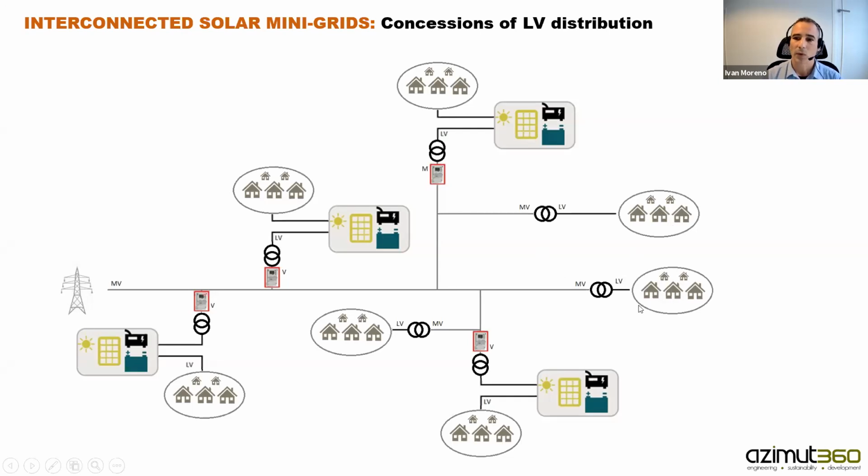So all the surpluses of the different sites could be shared and improve the electricity provided. It's always better to share or sell the energy surplus instead of modulating and reducing the plant production to fit the current load consumption. And here we could also have contracts with the utility if we have the meters to do that.